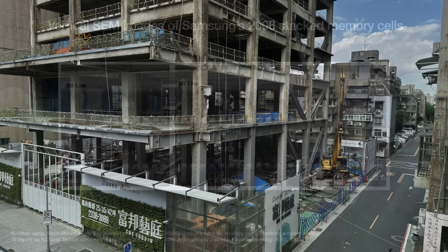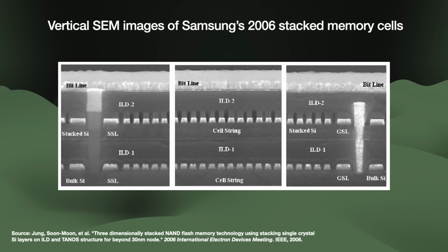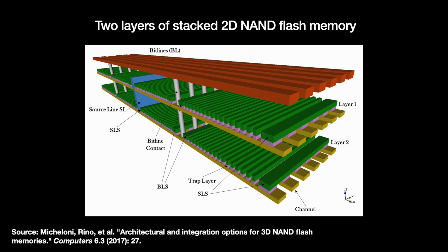One advantage of this 3D stacked architecture is that it carries over the older 2D NAND processes, so fabs are familiar with it and you don't have to buy as much new equipment. Moreover, you can test for bad memory cells before putting them into the stack. But there are also serious issues. Just ask yourself why they don't actually build buildings like this. Construction affects the completed layers lower down, the most concerning being heat damage.